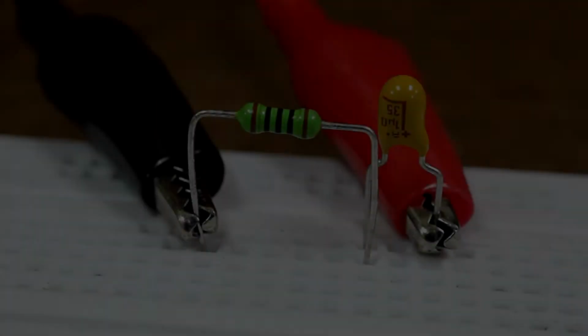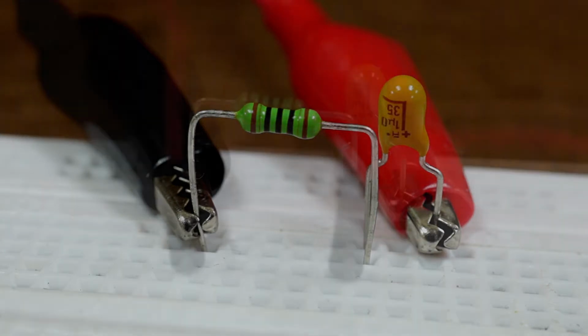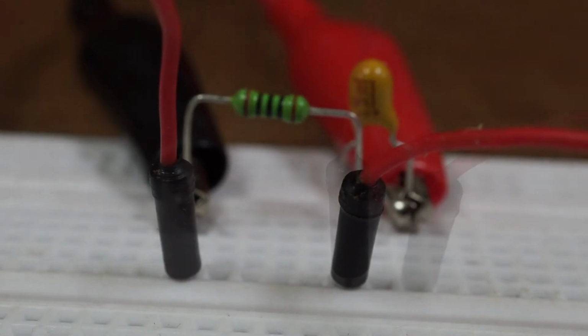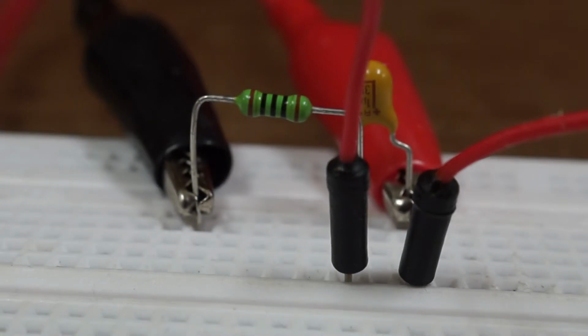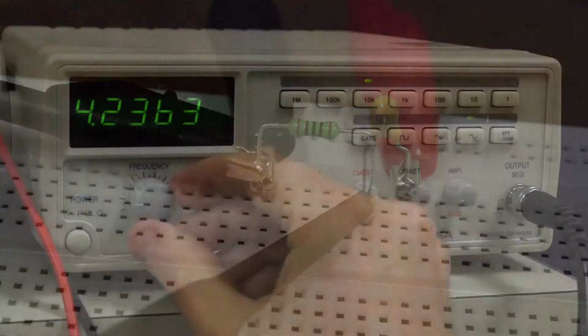The simplest circuit is called a passive RC filter, otherwise known as an RC circuit. It consists solely of one resistor and one capacitor, hence its name. Interestingly, this one circuit can do both the high-pass and the low-pass filter. If the voltage across the resistor is measured, it will show the trace of a high-pass filter.